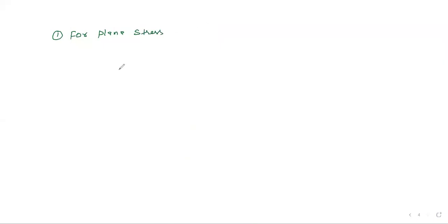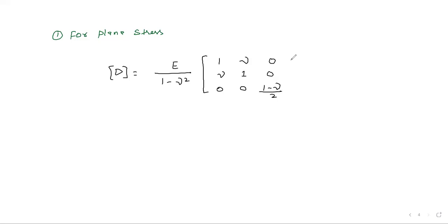For a plane stress problem, that D matrix is going to be E upon 1 minus nu square, times the matrix [1 nu 0; nu 1 0; 0 0 (1 minus nu)/2]. If they have mentioned that the problem is a plane stress problem, then the D matrix is going to be this.